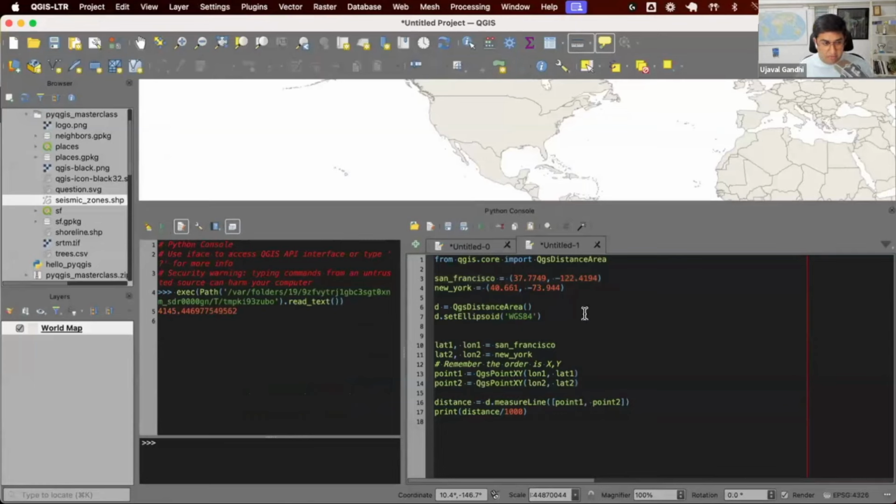Question, do we need to import the modules? Well, the QGIS Python console imports all of the QGIS classes. So when you start the console, it just imports everything in the QGIS classes. So you don't need to do this. It's a good practice to import it, because if you run this in processing script or in action or other places, they don't import all the classes. So your code will be more portable if you import it. But otherwise, in this environment, this console will always import this.